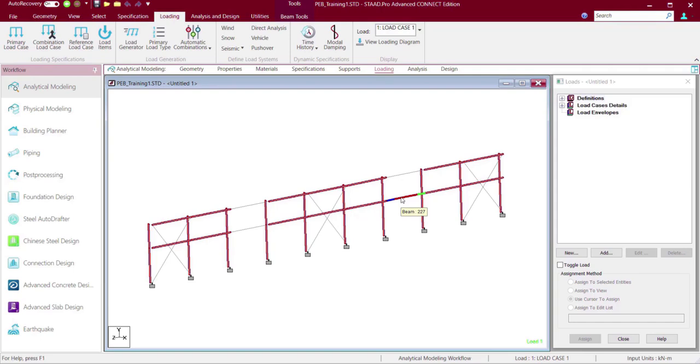In floor load also you have seen that we defined some grouping so that we can define the floor load exactly on those grouped panel names. Similarly, we can define the vertical panels and also tell it to apply some specific wind load on those panel areas only.